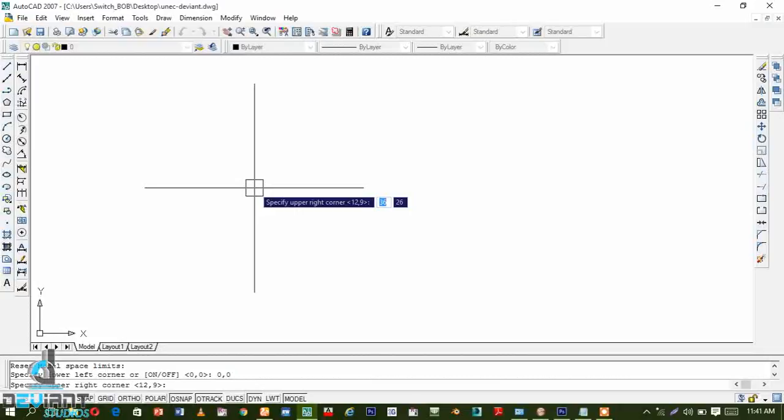It's not that I'm working with just one drawing, so it's advisable I use bigger spaces, like 100,000 by 100,000, which I can also use instead of a paper size. I can also use the size of A4, 210 by 297. That will be 210, 297. But now I want a bigger space, so I will use 100,000, 100,000. Then I'll press enter.